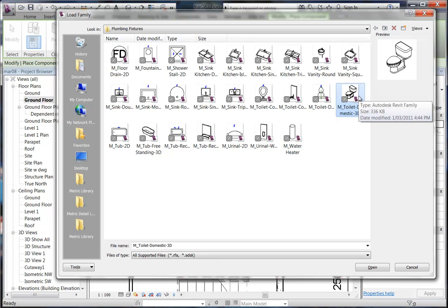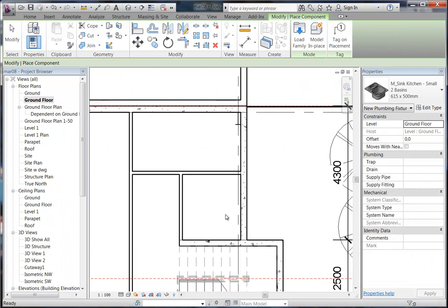In section? Yeah, sure. The 2D one has a view from one side in section, but not from both sides. So if you use the 3D one, you'll get views from all sides. It's a little bit messier than the 2D one, but for a project this small, the 3D one would be fine. In big projects, it's a real problem if you use the 3D toilet throughout, because you'll have hundreds of them, and you just want to keep the file size down where you can.